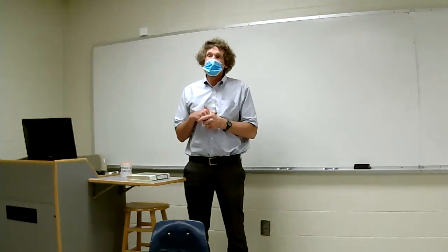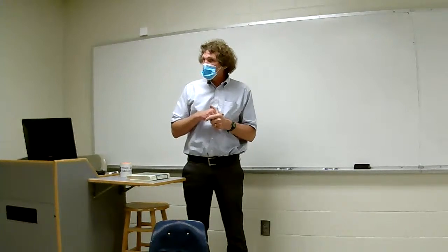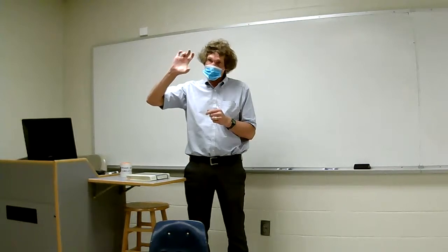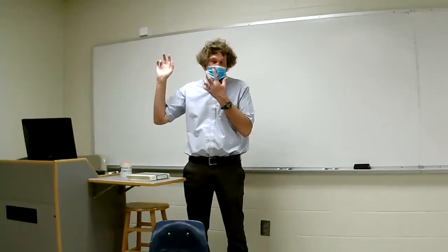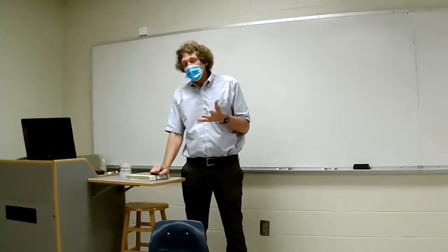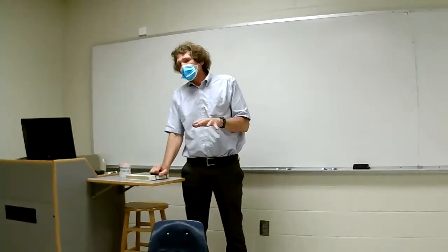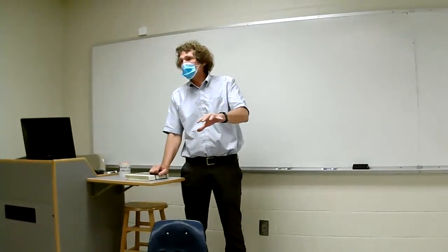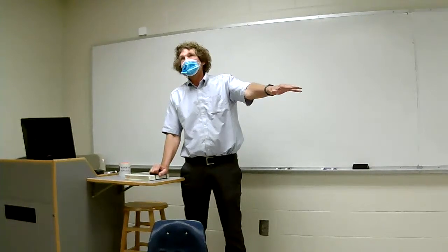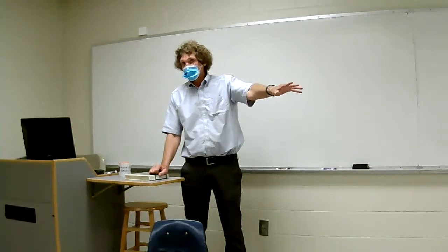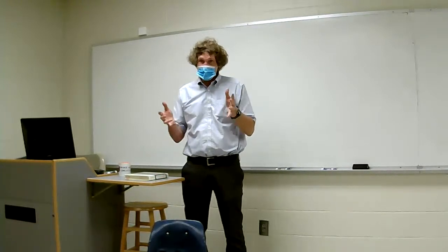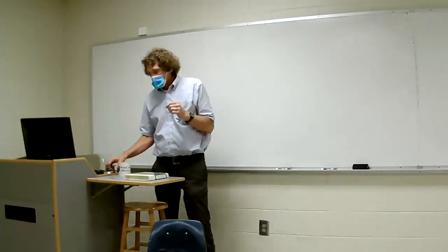Now there's a thing called Q. You remember with Q? The higher the Q, the sharper the filter response, but the higher the Q, the more overshoot right at those transitional frequencies. Those are the two things. I normally don't delve into that because this is really a circuits type of technique. In circuit analysis, you get a lot of this stuff. But in microwave design, you're really worried about matching things, line lengths, things like that, S parameters. So I'm going to forego that.